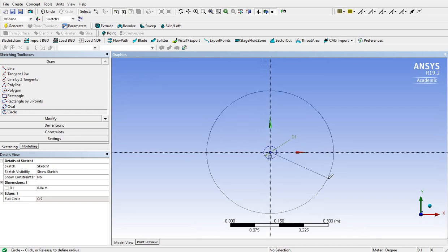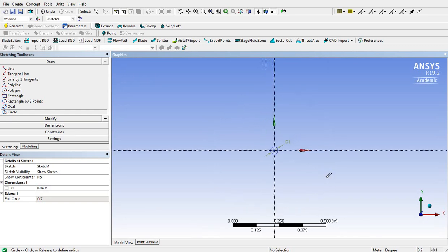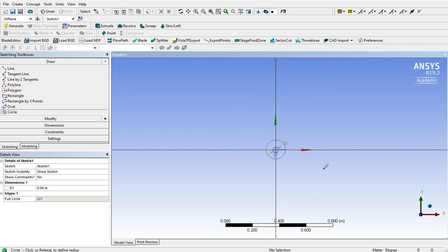But you're not limited to a circular external domain. You can do a rectangular external domain. You can do any shape. You can do a triangular external domain depending on your problem. Now, my object was circular, and I created a circular external domain because it would be easier to mesh. That's the only reason. Okay, it would be easier to mesh.